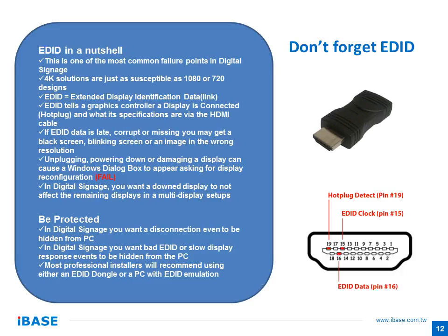That is a total failure in digital signage. This happens because the interface, like HDMI for instance, has this facility to detect that the screen is connected, right, and allow this handshaking to happen. We want to hide that from the digital signage players.